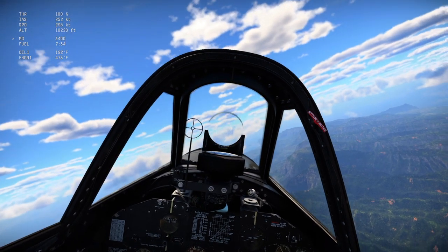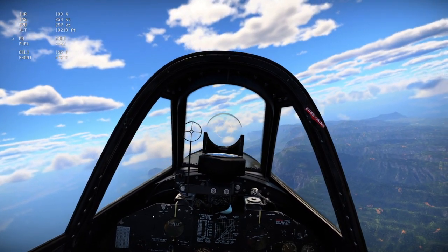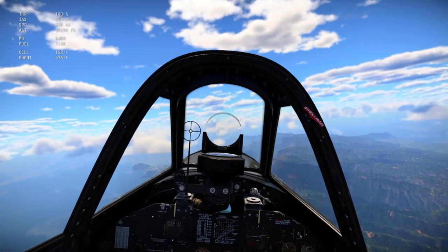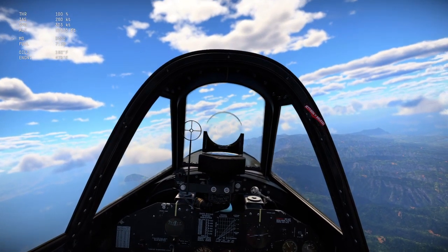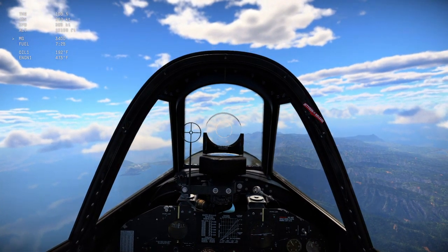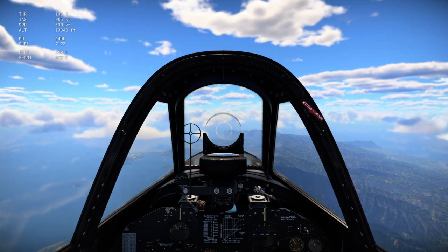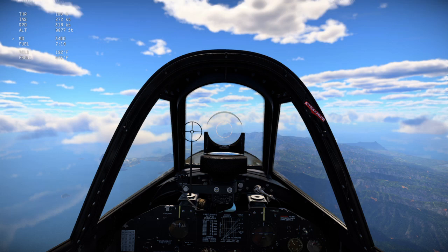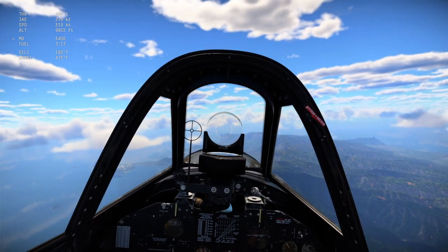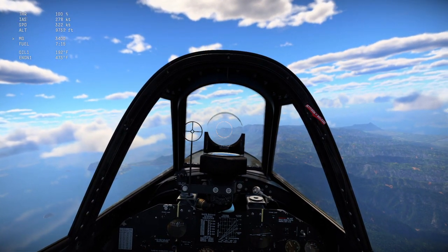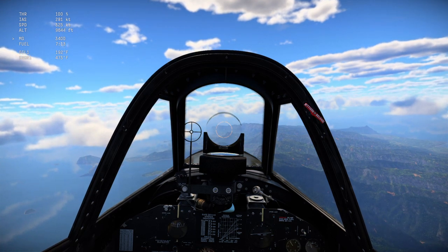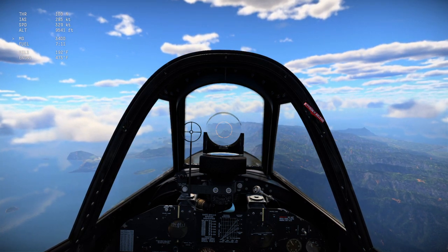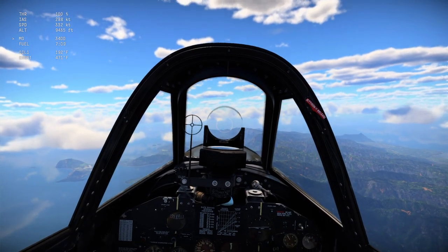So the difference in the radiators there is, with air-cooled or radial engines, since it's air-cooled, you don't have to have the radiators open as much, basically, because it's cooled by the air flowing through the engine. So with radial engines, a good percentage to start out with is 20%. With inline engines, a good starter percentage is about 40%.